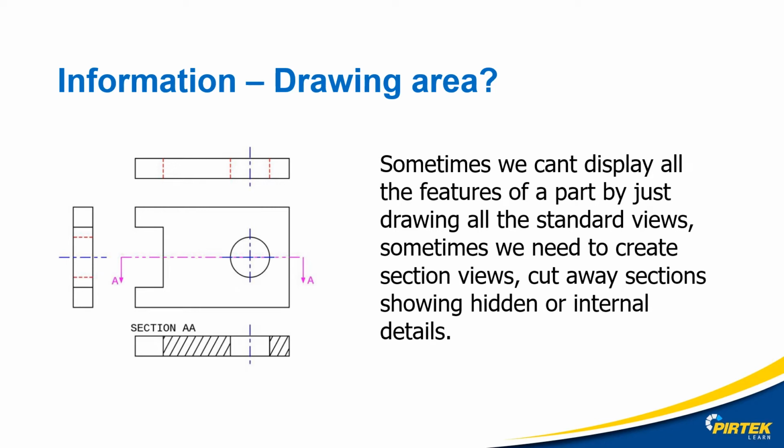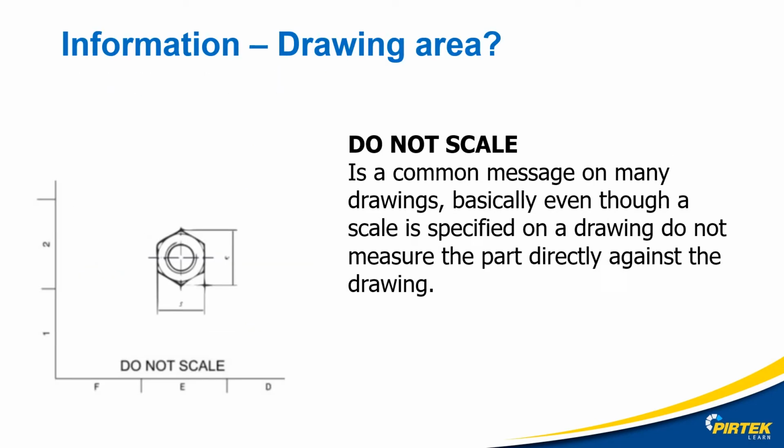Sometimes parts need to be cut in half so we can see the detail. These are called section drawings. Do not scale is a common message on many drawings. Basically, even though a scale is specified on a drawing, do not measure the part directly against the drawing.